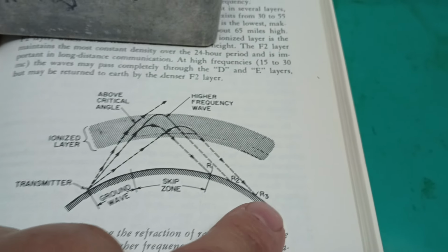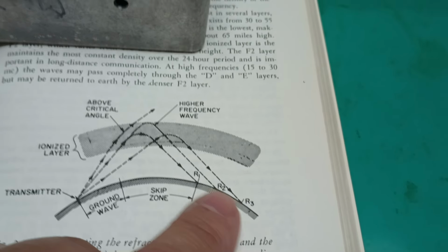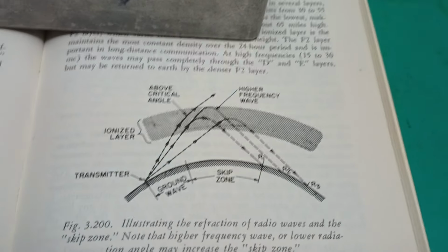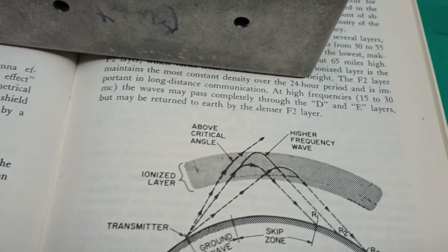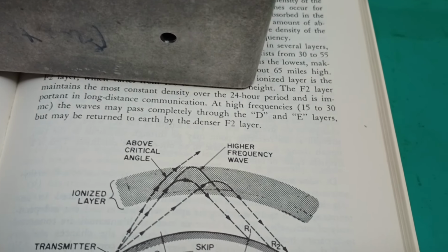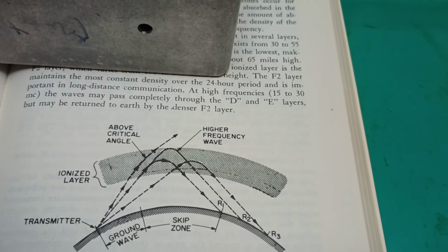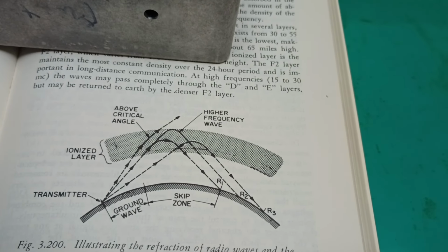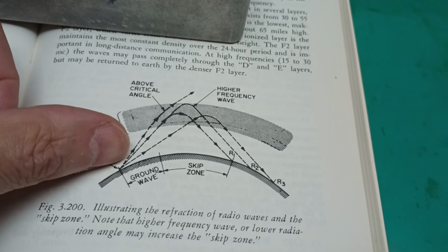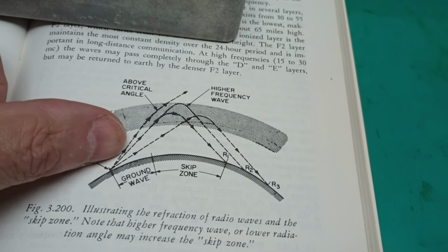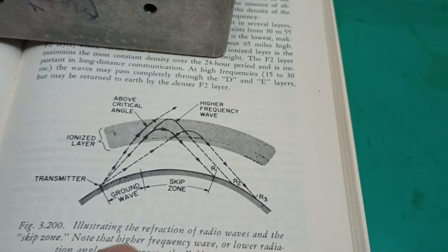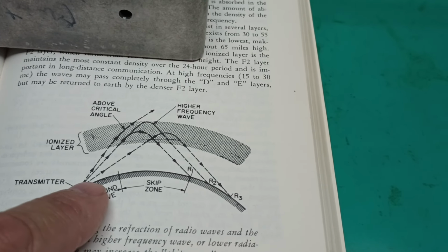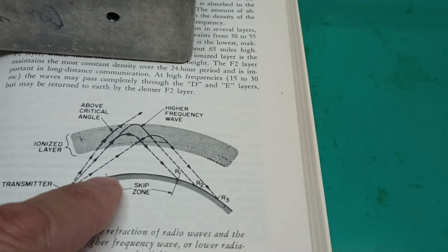Transmitter, distant multiple receivers. Note when we talk DX to Europe, we can talk to many countries at once. So whatever's happening is spreading out over thousands of square miles. Ionized layer, no surfaces, a layer. And Seybold says that much low angle, very strong propagation is because of a layer way down here from the Earth's surface to about 3 kilometers up, which causes low angle ducting and extending the radio horizon. And the radio horizon is a line between a transmitter going over where it contacts the surface of the Earth. It's a very low, shallow line.